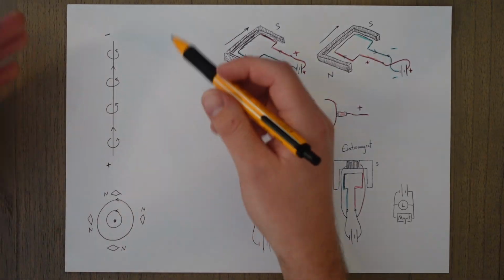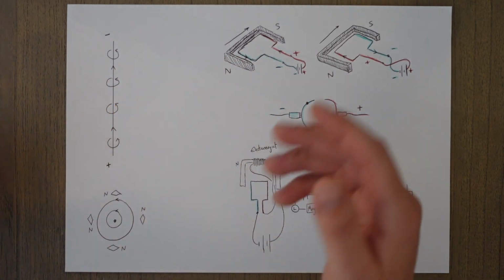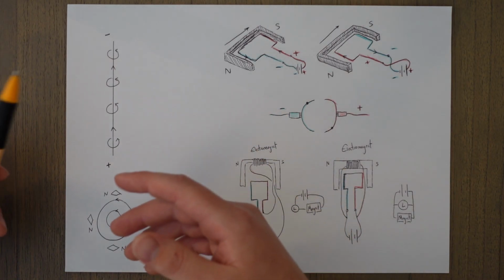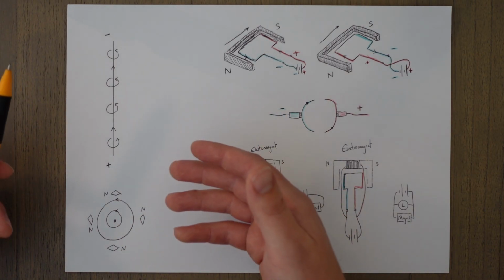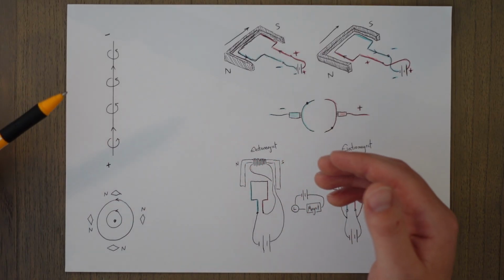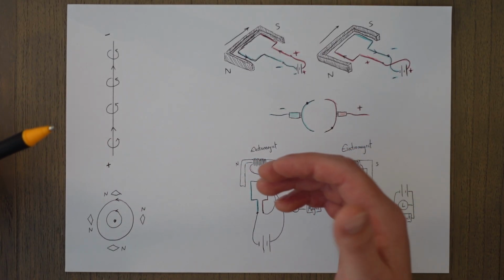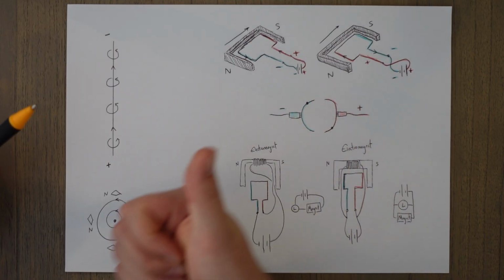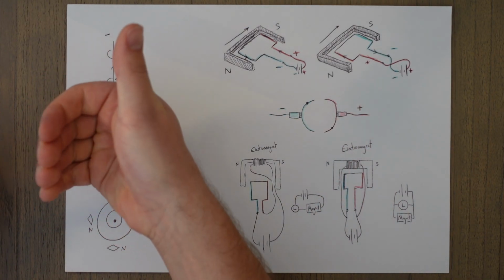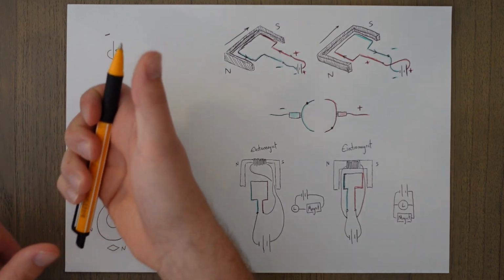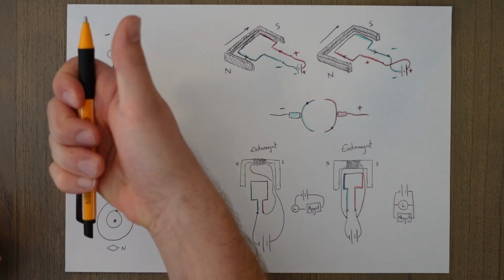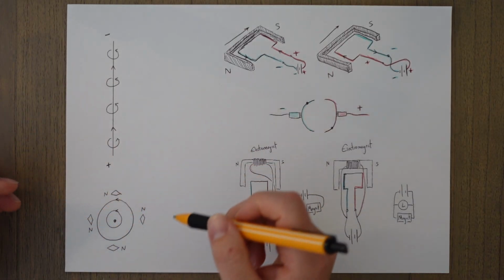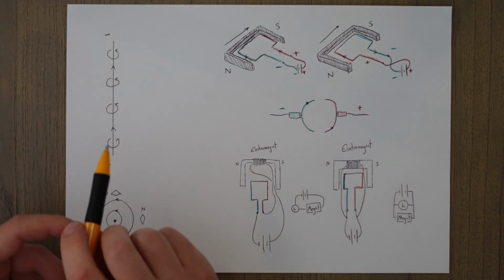The more electrons we end up putting through a wire, aka the higher the current, then the stronger the magnetic field that is created. And it does this in a specific pattern, which I like to use my right thumb for. I put my thumb up to indicate the current flow, and my fingers wrapping around indicate the direction of the magnetic field surrounding that wire. And the direction is the way that the north pole of a compass would be attracted to.